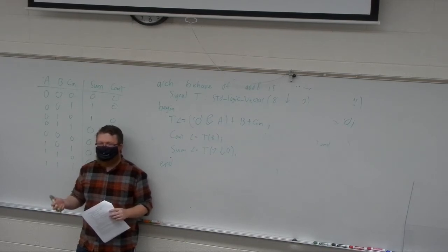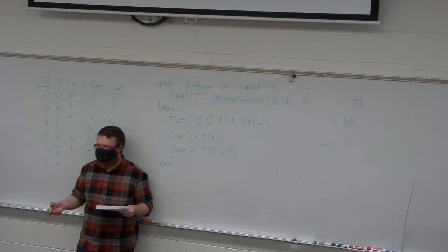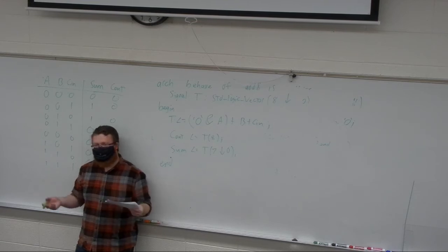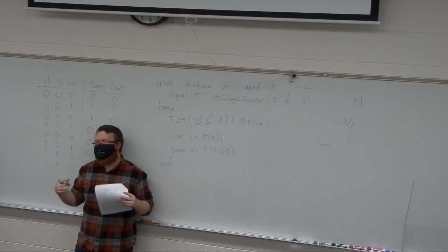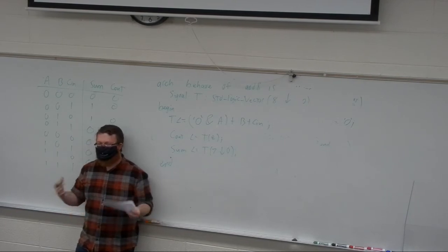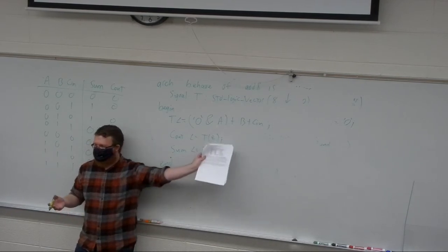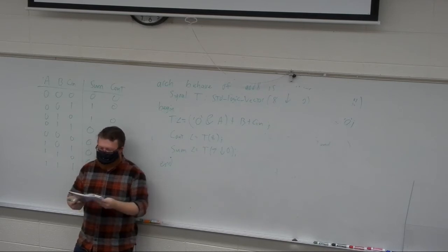So from those, if I'm importing, say, the IEEE unsigned library, I also tend to use the numeric standard library. This one has troubles adding those sometimes. So just be aware the type that you're using, whether it's signed or unsigned or numeric standard, each of these could cause you addition issues when you start building something like this in what we call an ALU, which is an arithmetic logic unit, which is what project 1 is all about.